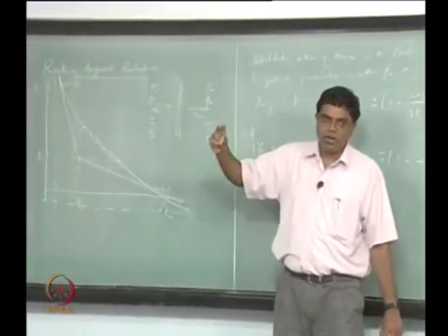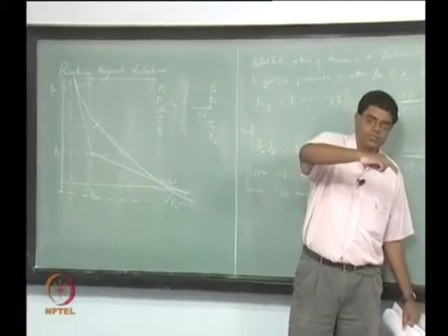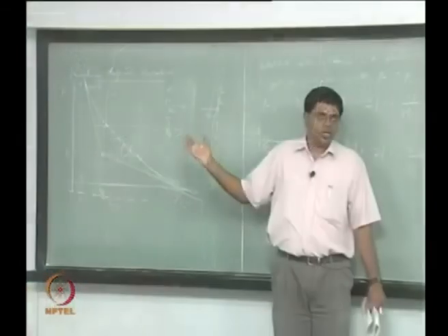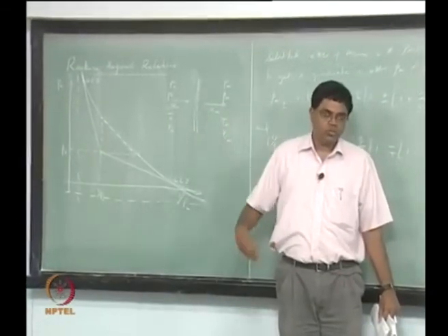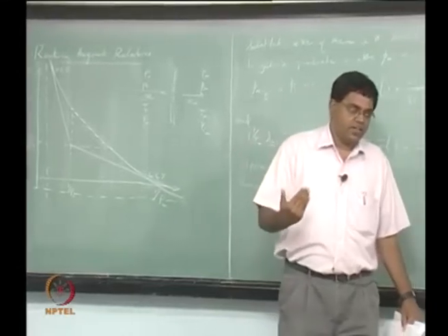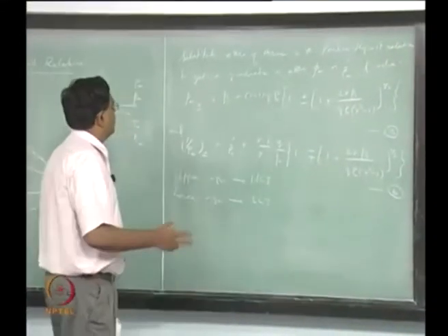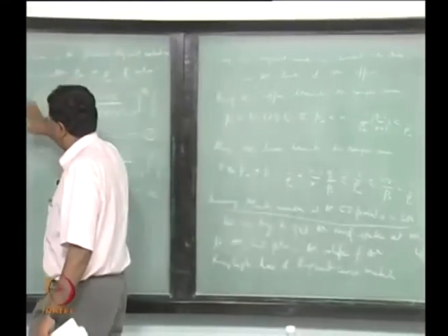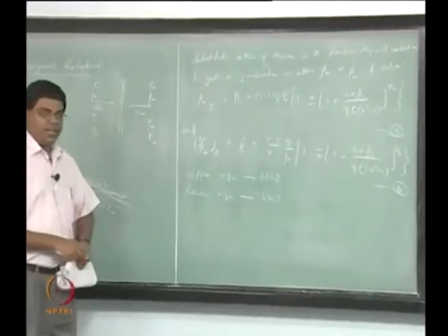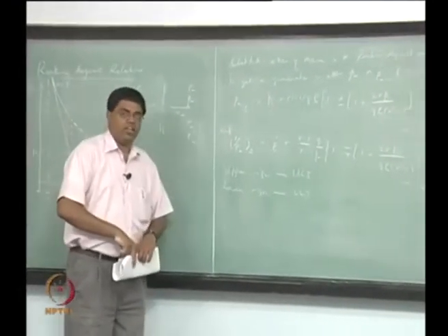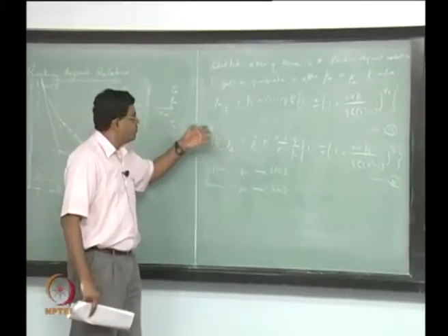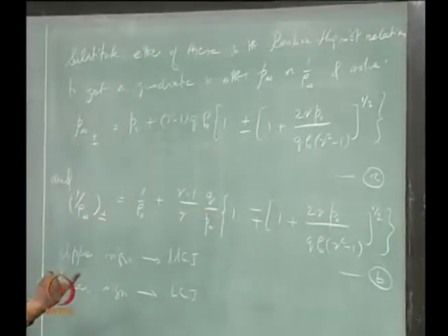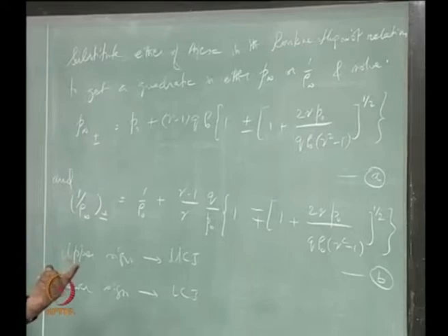That means we are looking at m dot, through which we will try to look for rho naught U naught, and m dot doesn't show up in the Hugoniot curve, it's showing up only in the Rayleigh line. So we should now go back to the Rayleigh line. We have substituted the slope matched information into the Hugoniot curve to get this, but can I now look at how the Rayleigh line is going to be if I plug these coordinate points in the Rayleigh line and then get an m dot information through that? You see what I am saying, okay.